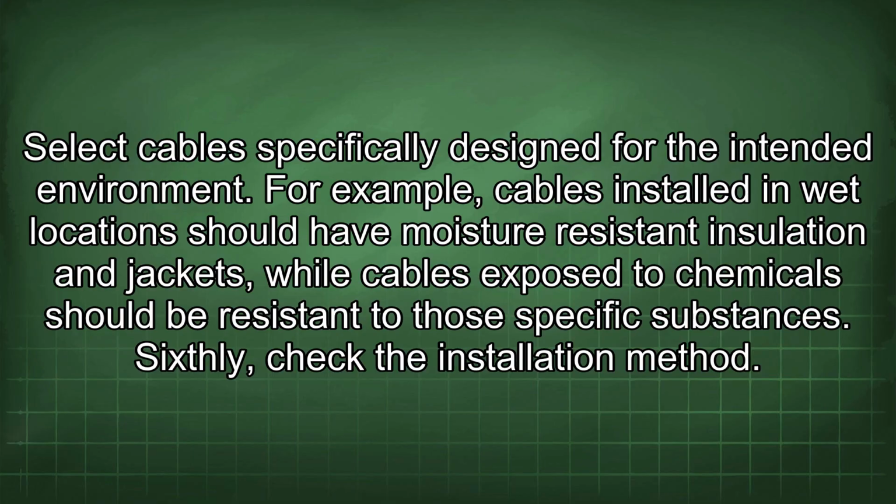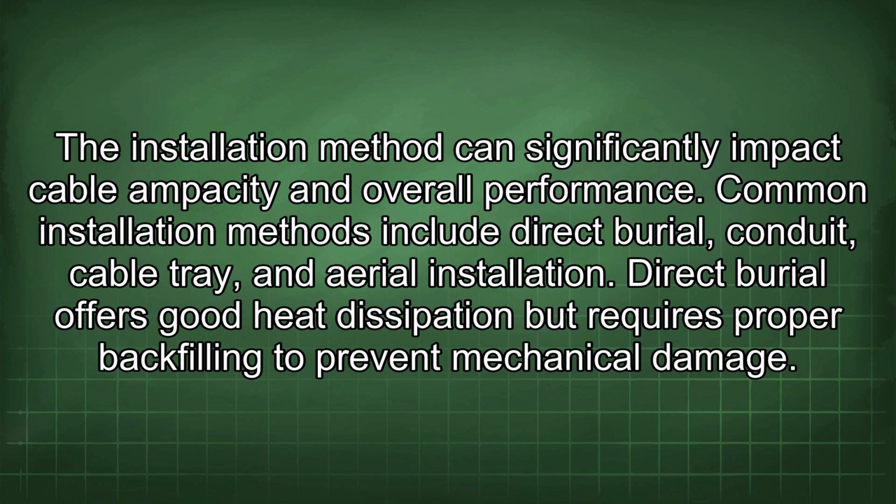Sixthly, check the installation method. The installation method can significantly impact cable ampacity and overall performance. Common installation methods include direct burial, conduit, cable tray, and aerial installation. Direct burial offers good heat dissipation, but requires proper backfilling to prevent mechanical damage.